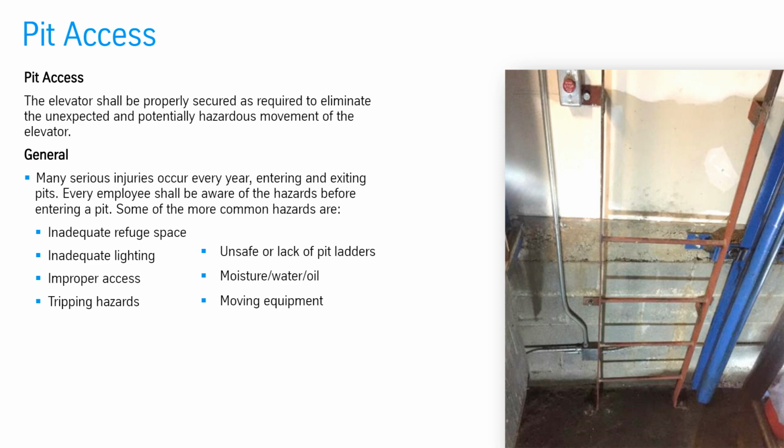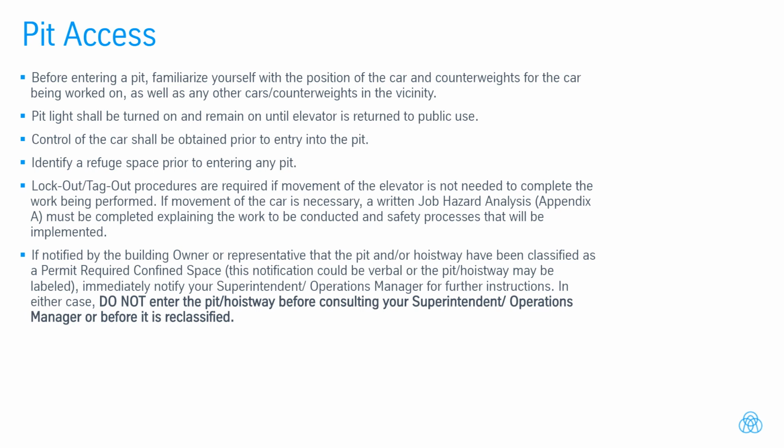General. Many serious injuries occur every year entering and exiting pits. Every employee shall be aware of the hazards before entering a pit. Some of the more common hazards are: inadequate refuge space, inadequate lighting, improper access, tripping hazards, unsafe or lack of pit ladders, moisture, water, oil, and moving equipment.